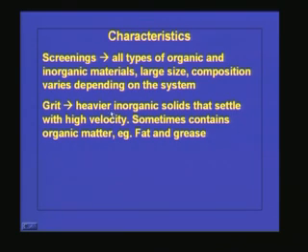So this is the basic character of grit, and sometimes it contains organic matter, for example fat and grease, because if the settling time we are providing is very high, then definitely along with the inorganic material, the organic material also will be settling down. So the grit may contain some portion of organic matter like fat and grease, and this grease can get attached to the inorganic material and it will be settling or floating along with that.